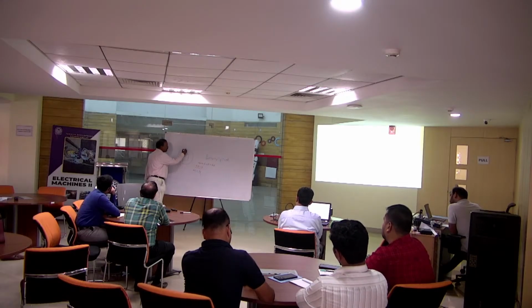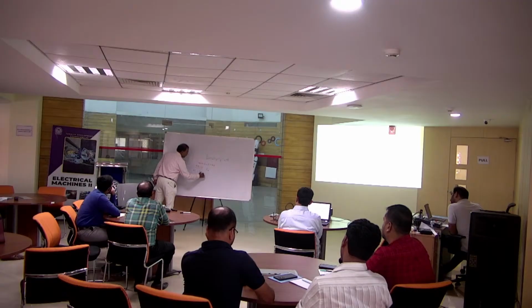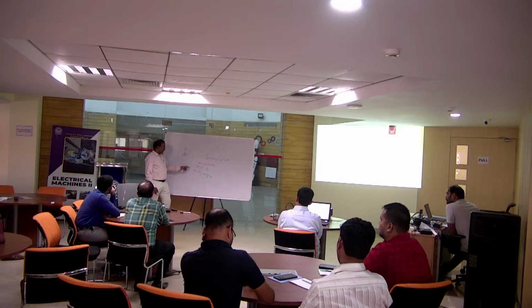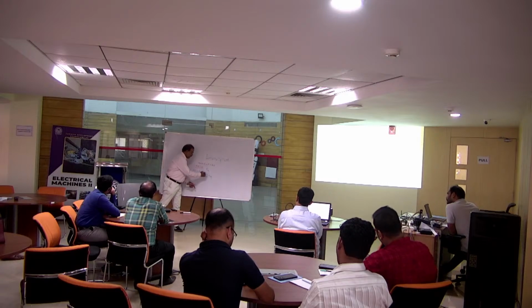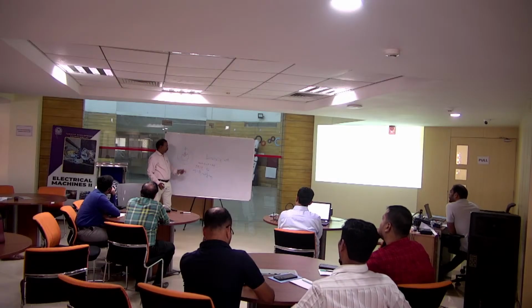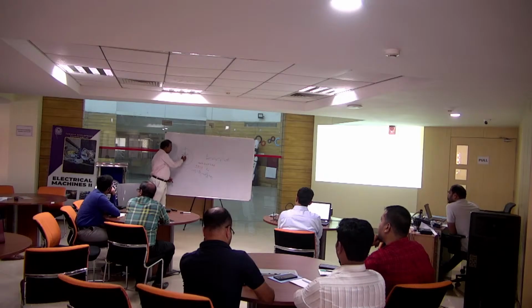Initially it was maximum, some F value, the maximum value. Now at this point it is Fm by 2 cos theta 1, for each of the two. So it will reduce, finally come to 0, then return in the opposite direction and become a negative maximum. So this is what you get here.